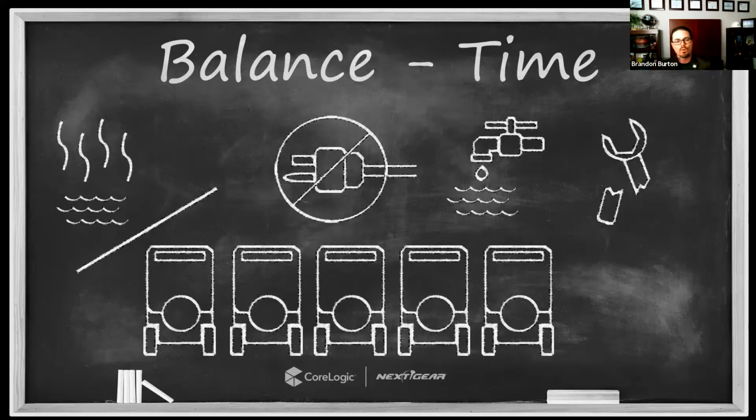First of all, when I identify that my system is not achieving the balance that I expected, the concept we talked about in episode 1 was asking the question why, at least 5 times. Why is humidity not in balance? All right, because evaporation is happening faster than dehumidification. Why is dehumidification not keeping up? Keep asking that question until you get to the base of the problem. Then once we get to the base of the problem, we can make the appropriate adjustment to address the balance, right?